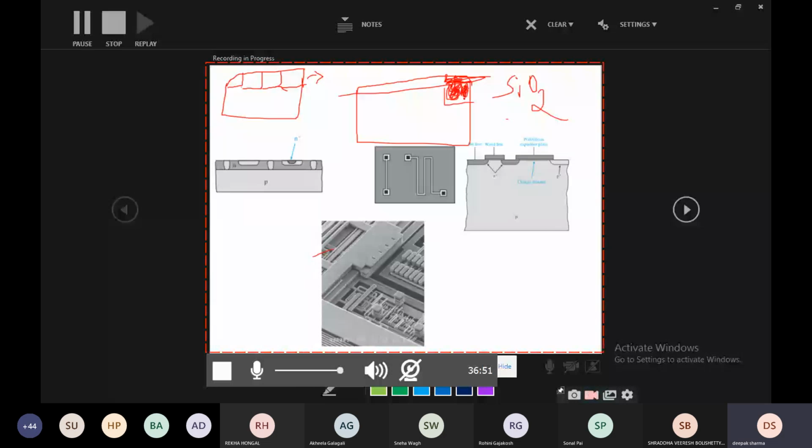So this part, the doping, or the ion implantation, is done, so that here we have source and drain. So this is source, this is drain, and then this is SiO2, correct? This is SiO2, and then above that we have gate, that is polysilicon, right? G for gate, right? Now what are we having? We are having a layer where inversion takes place.